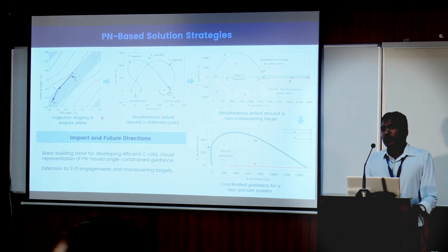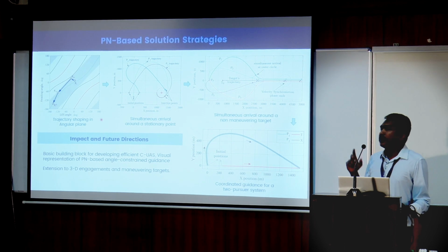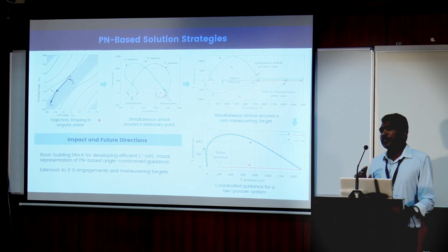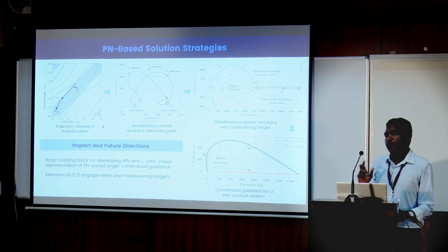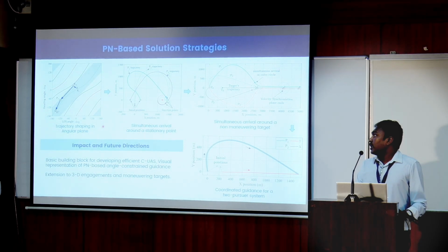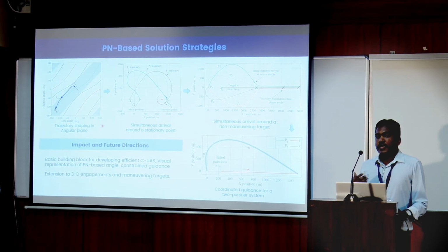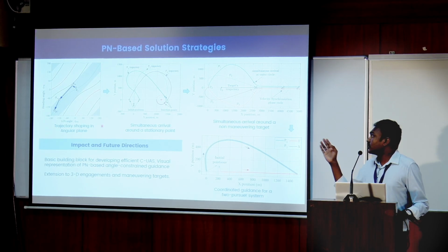Using this plane gives an advantage that the PN trajectories are just a straight line. Due to the linear relationship between the LOS and the heading, the PN trajectories will be just straight lines with the slope as the navigation gain. And it is also easy to prove all the existing results in the literature by just using geometrical arguments